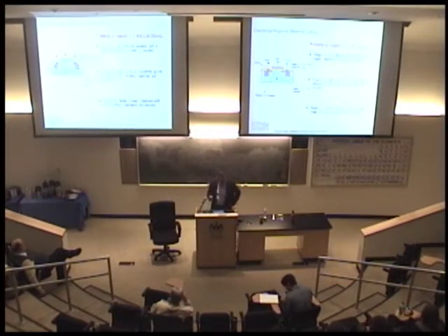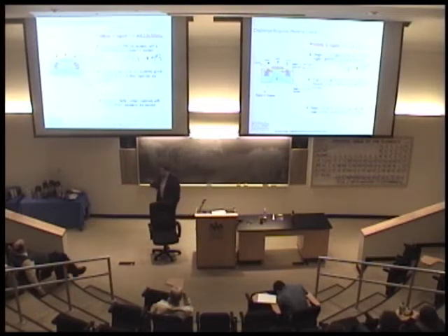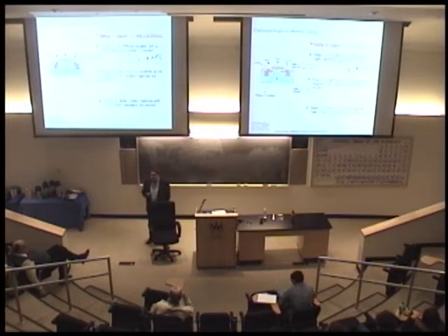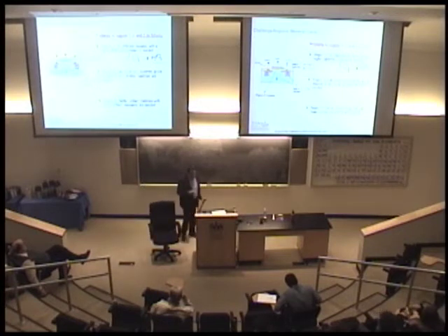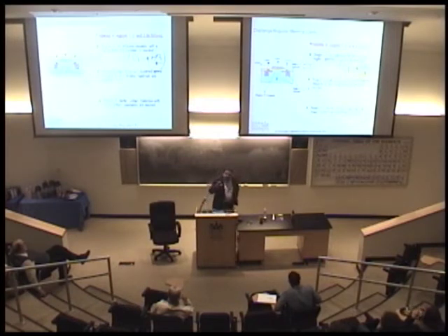Okay, so the problems are, we already talked about region 1. We need a high K dielectric, a better insulator basically, and that's done. Silicon dioxide is replaced by hafnium oxide. Intel is a very secretive company, all right? They never tell you, and they got input from a lot of scientists, but they also have their own engineers, and Intel has added something to hafnium dioxide. I believe, and most of the scientists believe, it's zirconium oxide, which makes sense to add. So it's not just hafnium oxide, but hafnium zirconium oxide, and I'll tell you why that's the case soon.